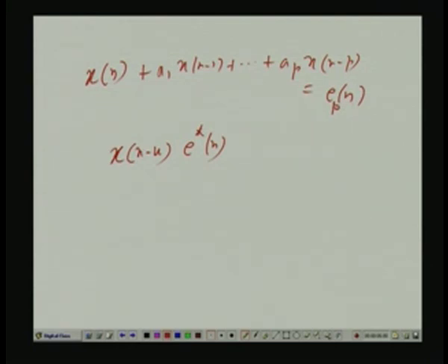So, just to indicate that a pth order model problem or pth order linear prediction has been considered, I just put a subscript p in all these. Okay. I will do the same thing a little later when further clarity will come. So for the time being let it be like this. If you take this, this is the inner product between x[n-k] and e star n, for k equal to 1 up to p. So x[n-1] with e star n, that must be 0.